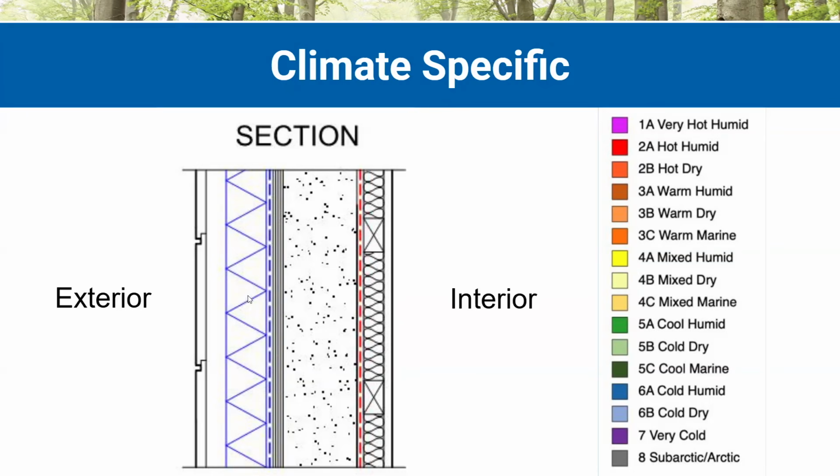If you're having exterior insulation, it's probably quite thin. You probably don't need very much of it. And an interior air barrier is helpful, but maybe not as needed in climate zone 1 or 2. Becomes more and more helpful as we're moving more north. So for climate zone 3, there's not a big difference. I would say you're maybe thickening this insulation level a bit more. I would still stick with the class 3 vapor retarder on the exterior for the more humid climate.